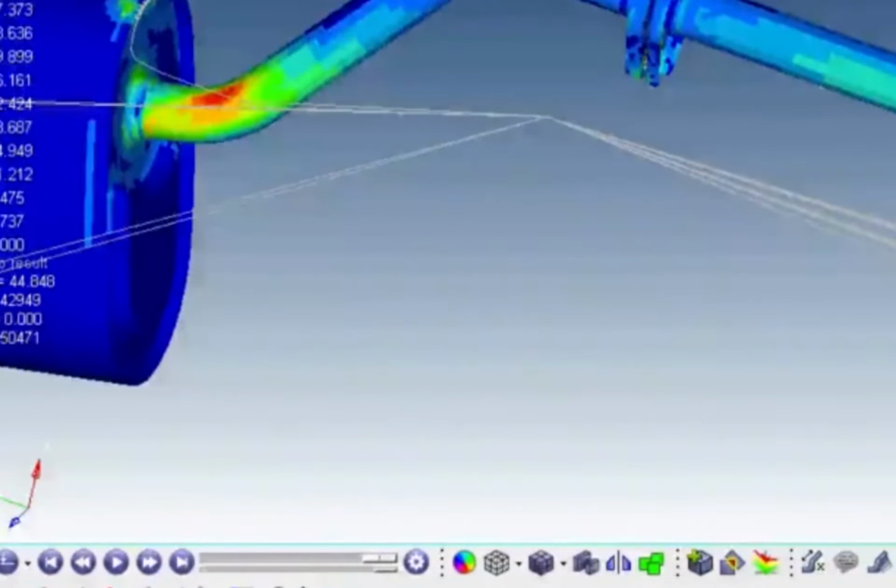Another thing that we calculate, which is pretty unique to our approach, is we take the RMS and we ask the user, do you want to estimate a peak response estimate from your random response? So if the RMS is 45 megapascals, how big roughly will the peaks be in a typical response history?